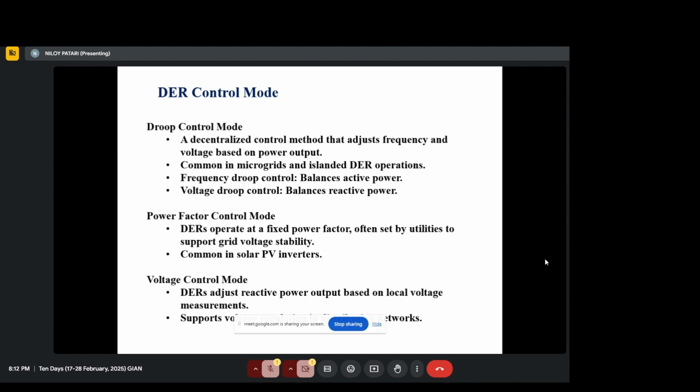This power factor control mode is not for a capacitor. In DERs, like if you have PV and battery, you connect that PV and battery through certain converters to the grid, right? And those converters, which are power electronic converters, are able to modify active and reactive power instantaneously. So why is it instantaneously?